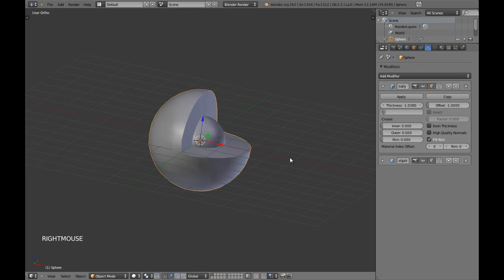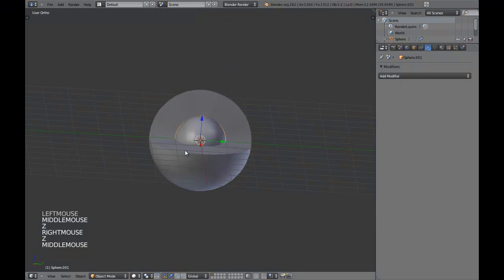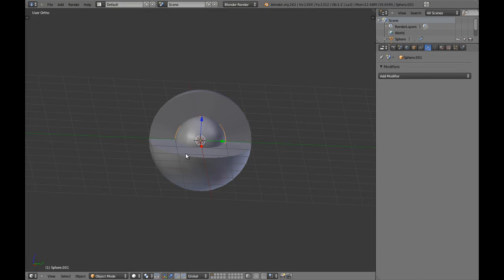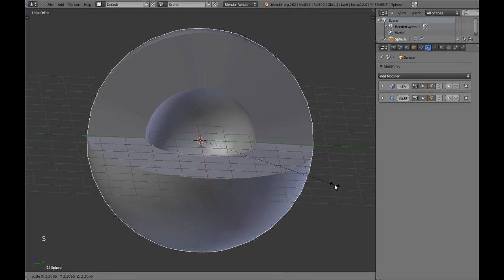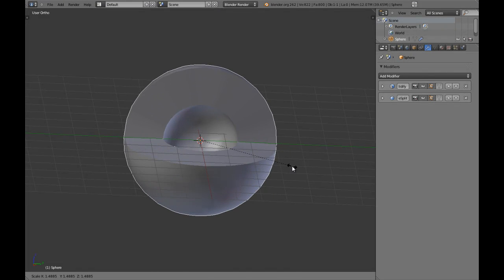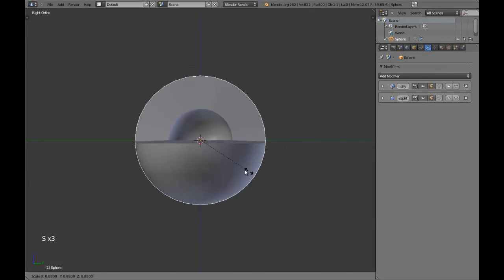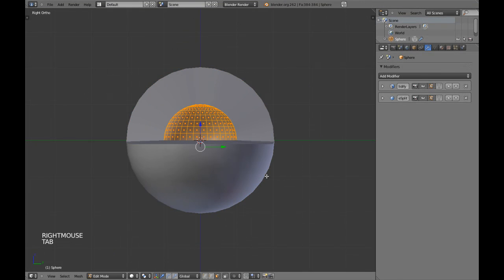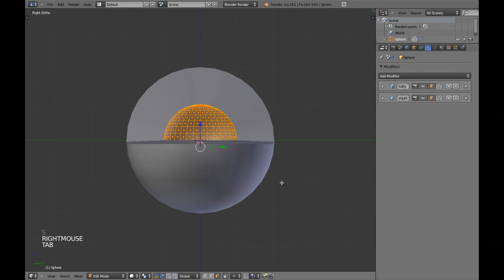this is not a big deal, but there's something that could modify the behavior of Solidify. For example, if you scale objects out of edit mode, you will see that the behavior of the thickness is changing a lot, but it's not the same as when you do it in edit mode.